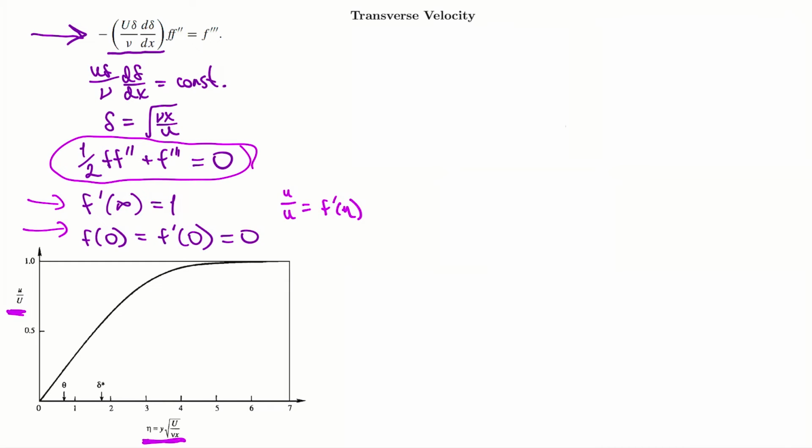That's awesome. Now our transverse velocity we can solve for as well, right? So that's the velocity in the y direction, moving normal to the surface, because v is negative psi x, which I've shown down here. So therefore we can sub in because we have our velocity profile now.